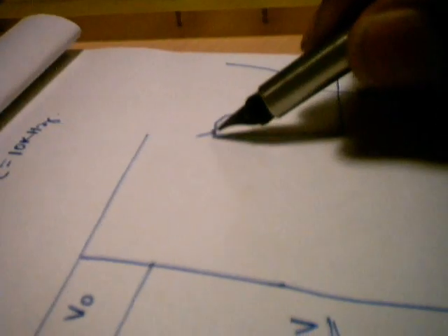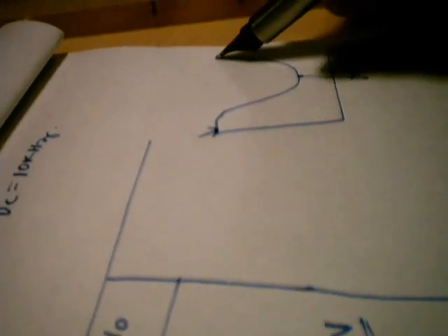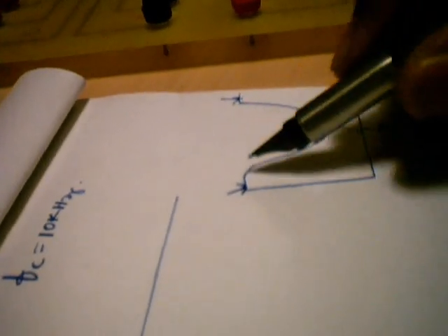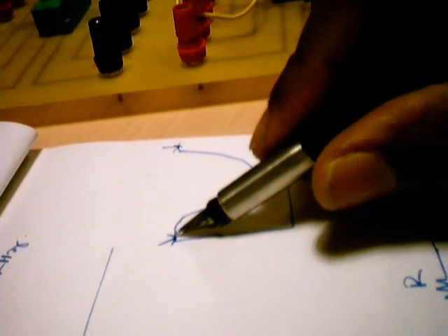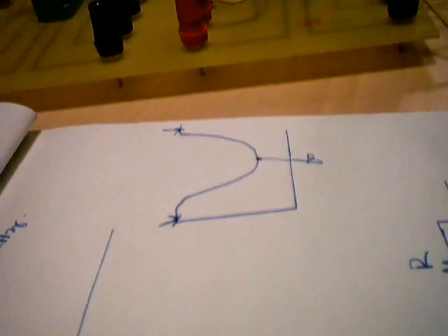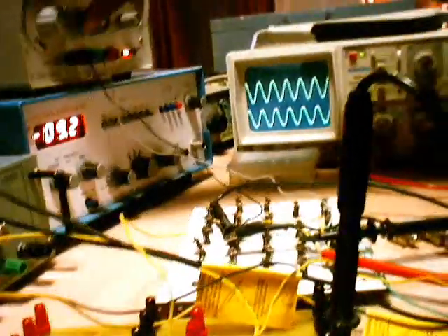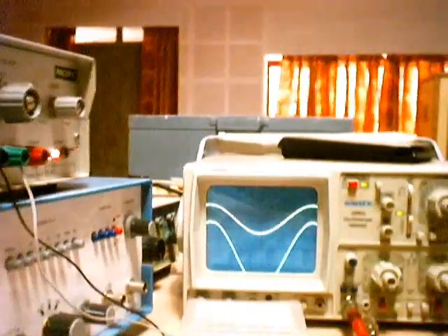So in order to find the bandwidth and all those things, you find what is V0 max at this point and V0 max in this passband, because there are two possible passbands. We need to find what is V0 max here, V0 max over there. So let us find V0 max by reducing the frequency below F0. So I reduce the frequency below F0.